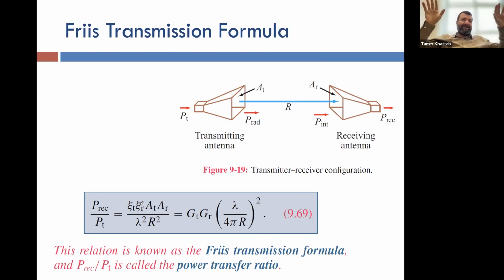So you are not inside a building, you are not around buildings, you are not very close to the ground or earth, right? In the case that you have free space, no obstacles, nothing reflects your signal, and the transmitter is sending a signal which is being intercepted or received by a receiving antenna, the analysis that we do here is called free space propagation analysis, or they call it the Friis transmission formula.